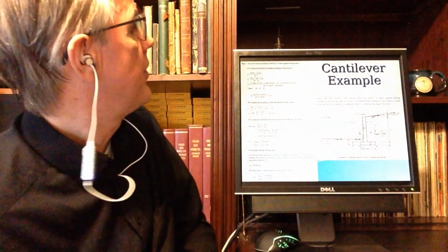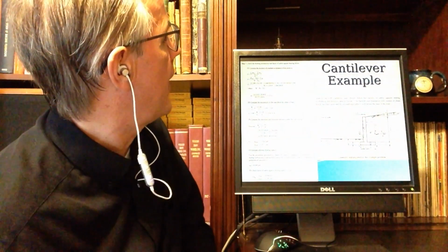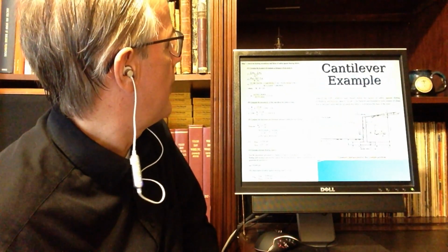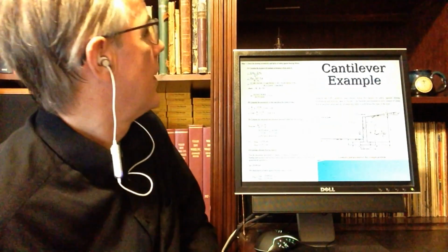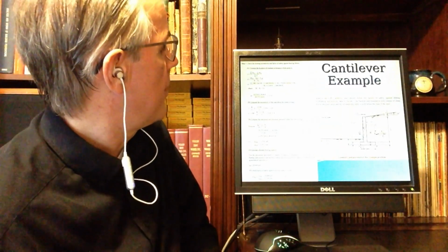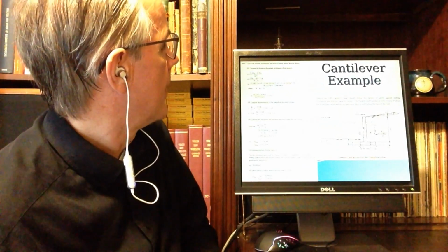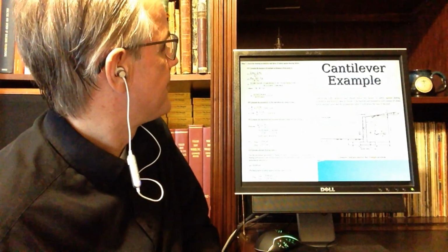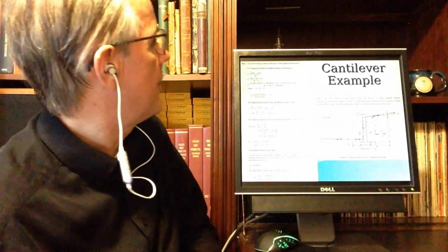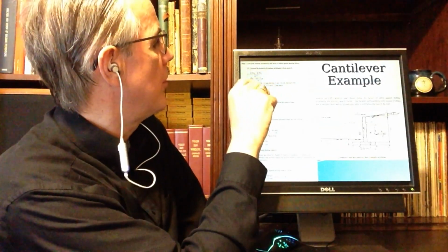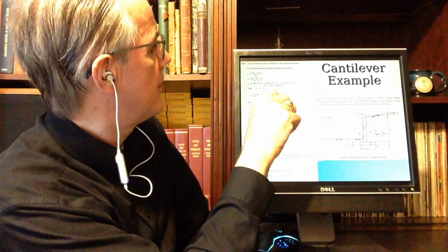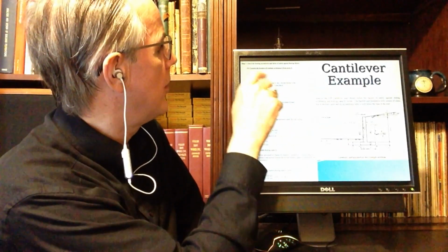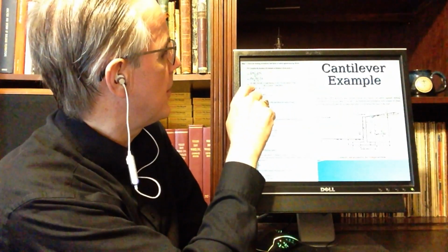Okay, next, check the limiting eccentricity and factor of safety against bearing failure. All that involves is this. I'm trying to compute whether the resultant is in the middle third. That's fairly simple. Basically, it is equal to the resisting moments minus the overturning moments, which I've already computed, so you just plug and chug.